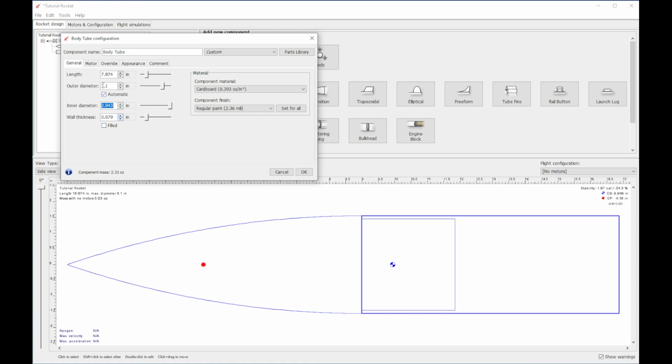Sorry, I take it back. It's only going to automatically calculate the outer diameter. Inner diameter and wall thickness are related. If I make this 0.1, it should recalculate that inner diameter to 2.9. I'm going to actually measure that value and see what we get. Hopefully it comes out pretty close to what the simulation wants it to be, so that we don't get any body discontinuity errors, which is a thing we'll cover in the simulation portion.